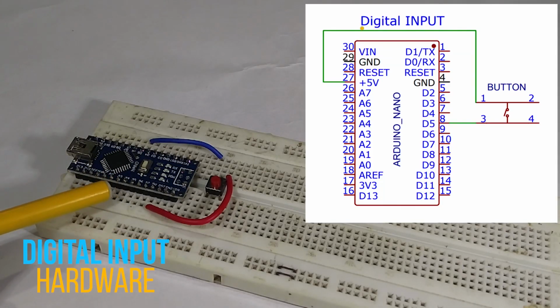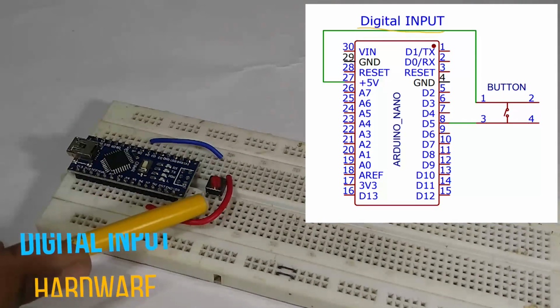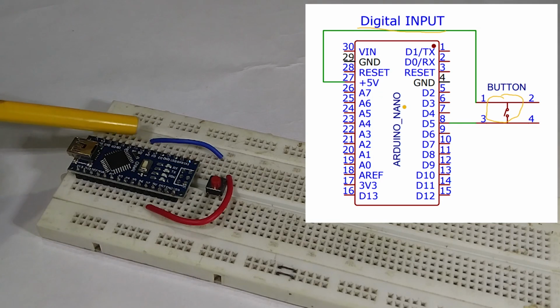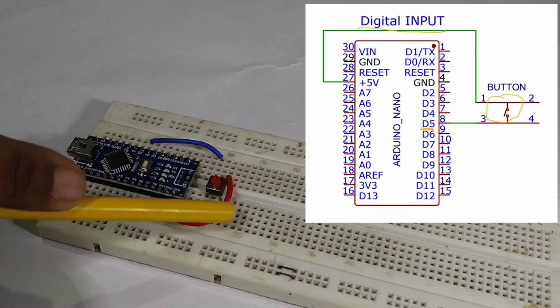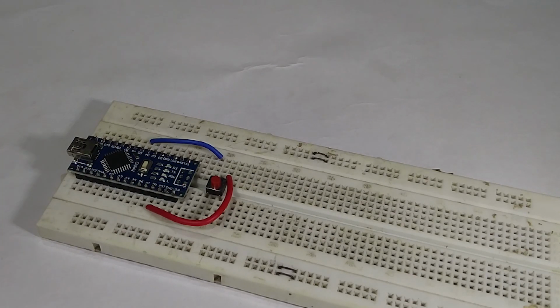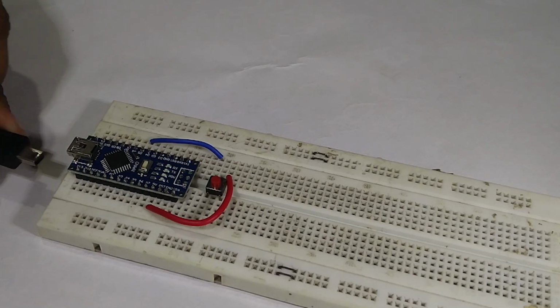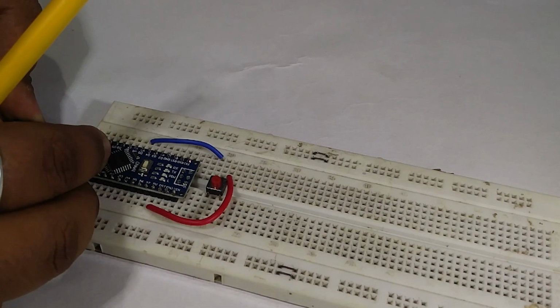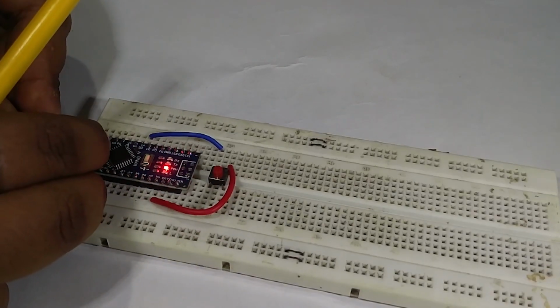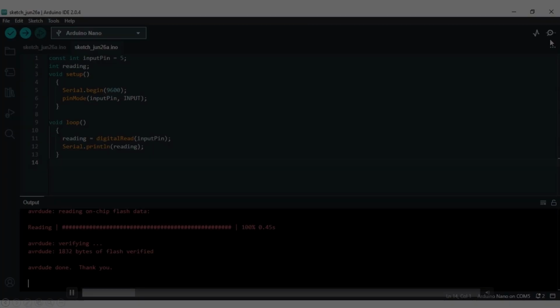So here we have the circuit of digital input. We just need a push button. One end of the push button is connected to pin D5, and the other end is connected to plus 5 volt. Now let's connect this Arduino to the PC, and I have already uploaded the code to this Arduino board. So now let's see the digital input in the serial monitor.